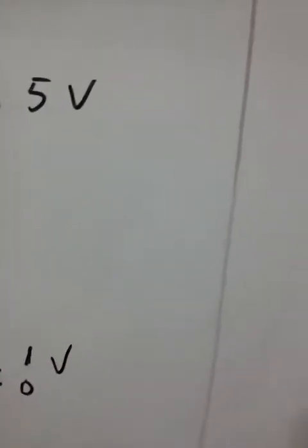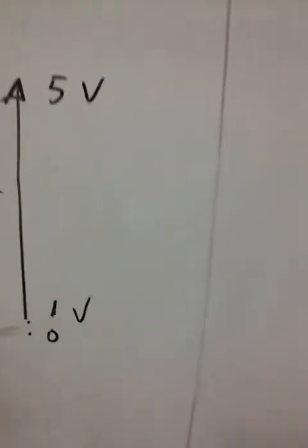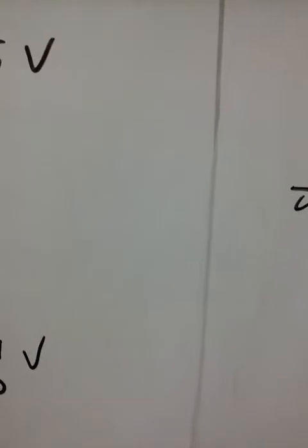Because from there, you can use this graph. Let's say from 1 to 5 volts, we're starting from 0%, or you can take any set point, let's say now from 0 to 100%. From there, we can calculate the output voltage, since it's a linear process.